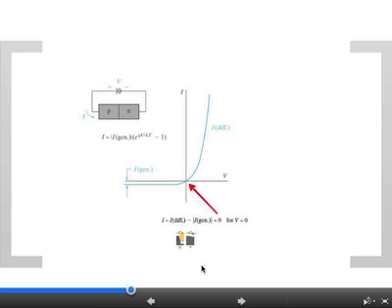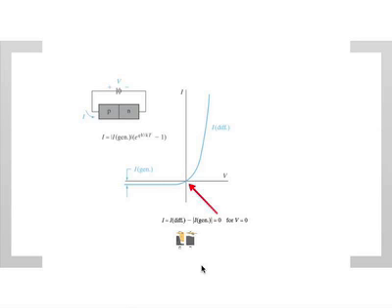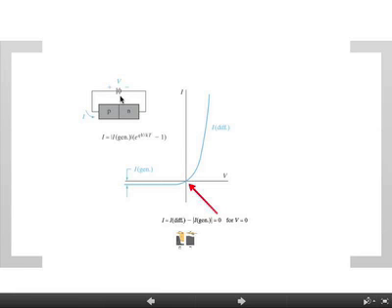Okay, so the diode equation, and we'll derive this in a few minutes, looks like this. So this is the picture. You have a PN junction. You apply a voltage V. What is the current that flows through? It essentially looks like that, which you might have seen before. You have some constant here, which is the generation current that we talked about, multiplied by a term here, e raised to qV over kT minus 1. V is the applied voltage. And if you plot it, this is what it looks like.